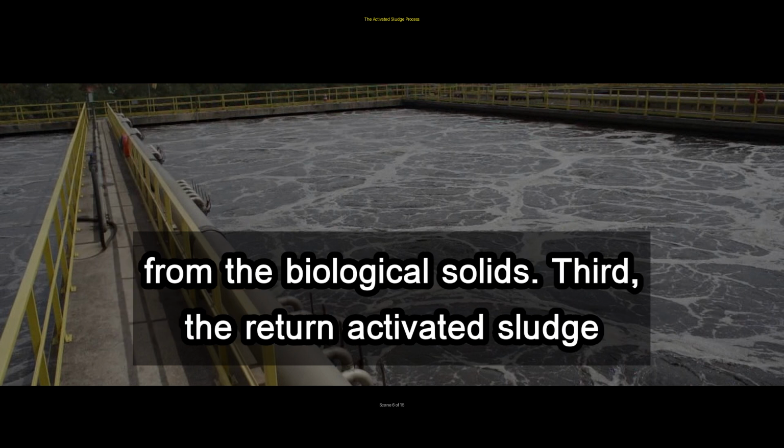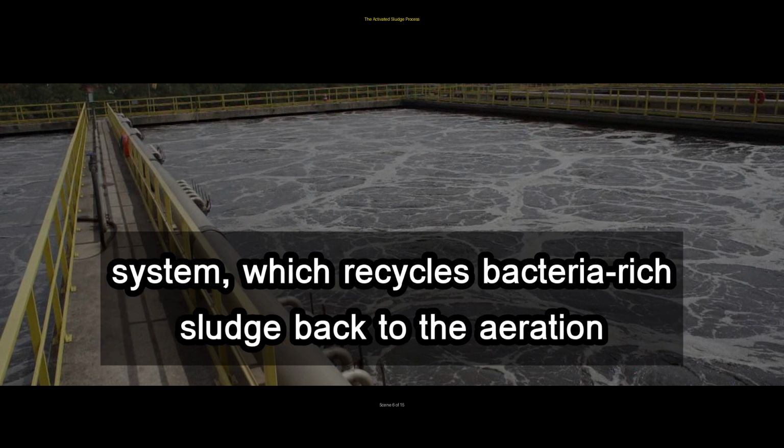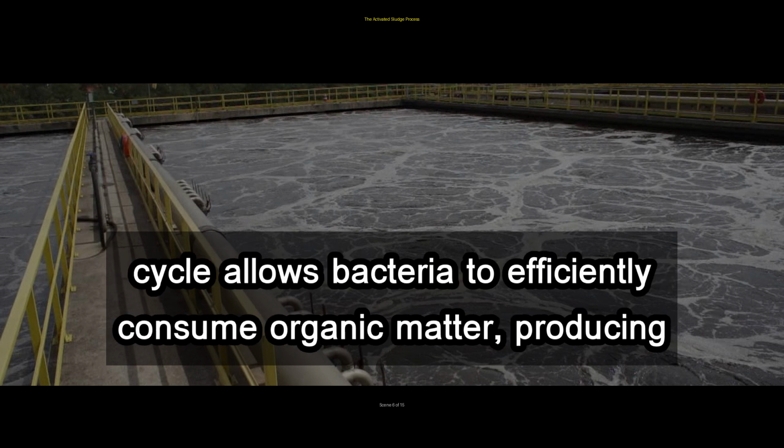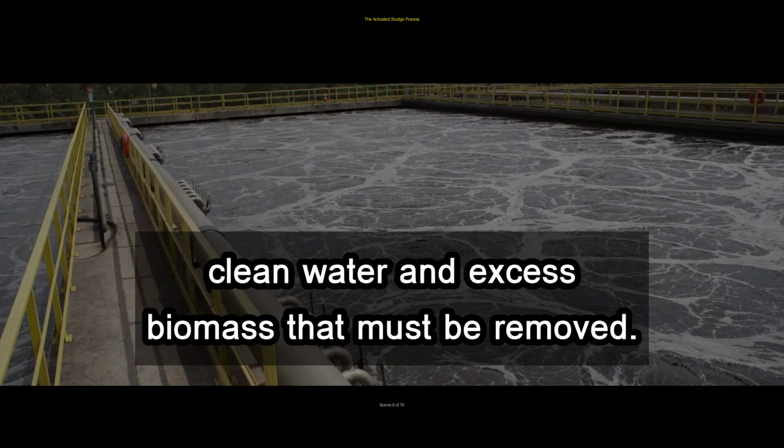Third, the return activated sludge system, which recycles bacteria-rich sludge back to the aeration tank to maintain an active microbial population. This continuous cycle allows bacteria to efficiently consume organic matter, producing clean water and excess biomass that must be removed.